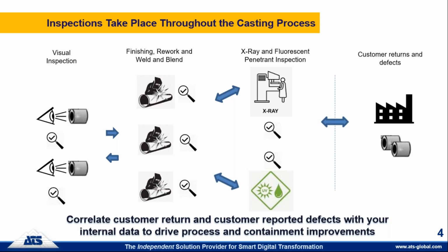If you work in an aerospace type of environment and you have expensive castings or complex castings made out of titanium, magnesium, etc., a lot of times there is an opportunity to repair the parts, do some welding and blending, etc. Even if you don't repair the parts, generally if there's some minor defects like removing flash or grinding a gate off, that type of thing, that process or an actual weld and blend generally means that after the parts have been worked on, they cycle back either through visual inspection or else they go through a more complex type of inspection such as FPI or X-ray, etc.